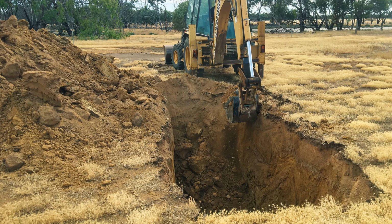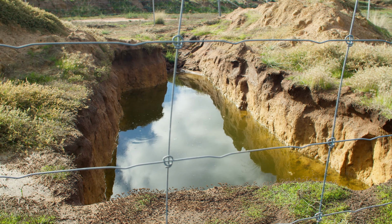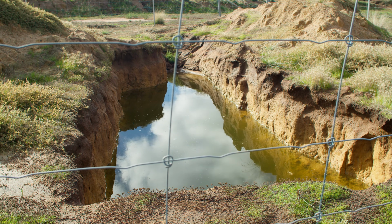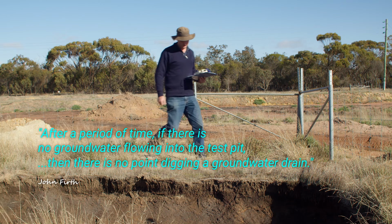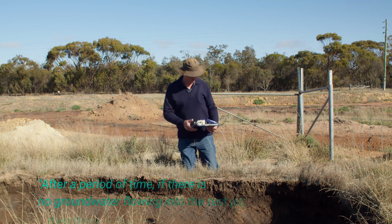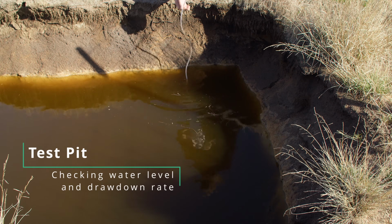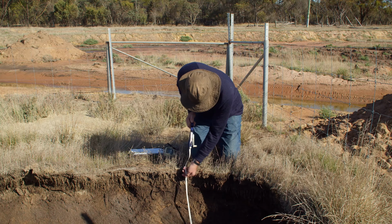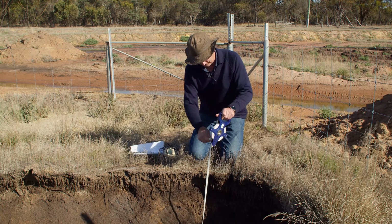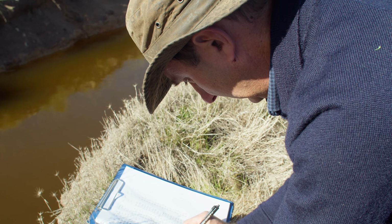When digging a test pit, what you're trying to do is a number of things. First of all, you're trying to find out if there's any water there. What is the depth of the groundwater? We're also trying to find out at what depth the groundwater is flowing into the test pit and what volume of water is coming into that test pit. So we want to know the discharge rate of that soil. By digging test pits, you also get an understanding of the soils you're encountering on that particular location and at what depth they are in the landscape.